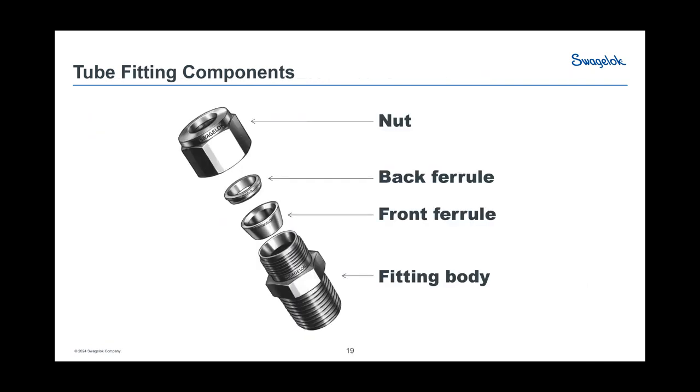So let's talk about tube fittings, and Swagelok is the founder of the 2-ferrule fitting. This is really our bread and butter, and it's designed for this. I want to talk about why this is the most appropriate connection style for small molecule gas. Again, I've mentioned before that most of the products being used in all the downstream areas of hydrogen are going to be smaller piping sizes.